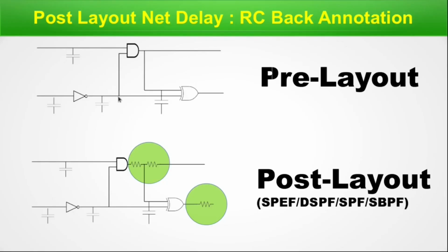This is a node, this is a node, this is a node. Such nodes will generate multiple subnodes. These subnodes will be connected to the parasitic resistors, capacitors, and coupling capacitors, because these are metal routes in actual practice, and the coupling capacitor will show the neighboring effect.